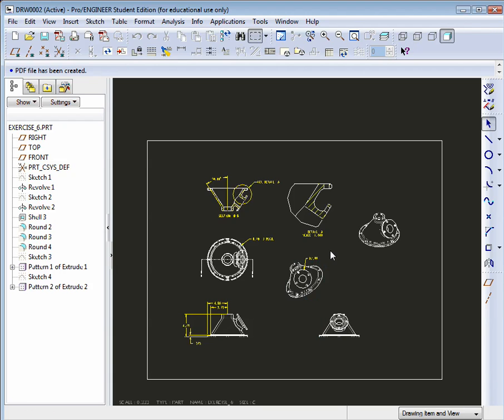Okay, let's draw a border in here. Now, before I start drawing a border, there are these two little options here. One of them is to enable sketch chaining, and the other one is to remember parametric sketch references. Both are very helpful, especially if you want to make sure your lines are horizontal and vertical or straight or attached to different entities. So I like turning both of them on. And here's how it works. We're going to draw a border surrounding this.